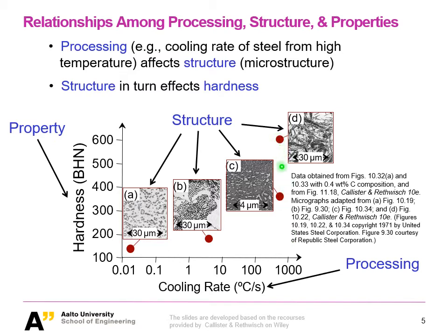But you could have two types of martensite. If you're aiming for super high strength, you can choose what we call fresh martensite, or in your textbook it's just called martensite, which is this needle-like martensite with a very tiny microstructure and a very distorted crystal structure, the BCT structure. And of course, from the same cooling rate, if you just do a little bit of post-processing, a heat treatment with quenching and tempering.